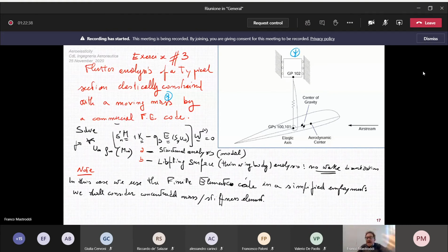Okay, so at the end we will obtain mass and stiffness matrices, but these are not corresponding to a finite element discretization, but to an originally discretized system in space, like a rigid body concentrated in a point, having a mass and inertia with respect to that point, so translating and rotating. Okay. We can use the finite element code also with this reduction.